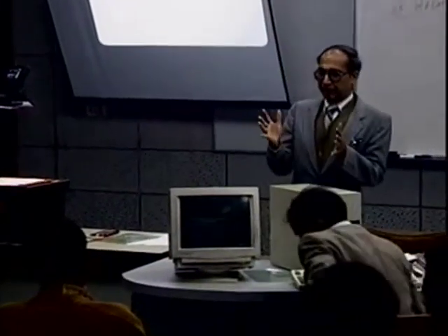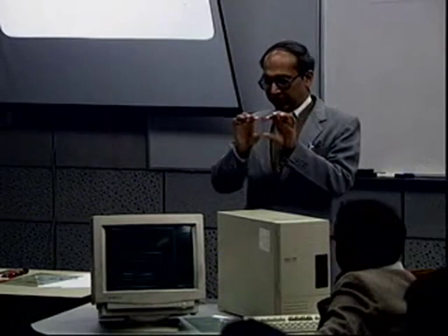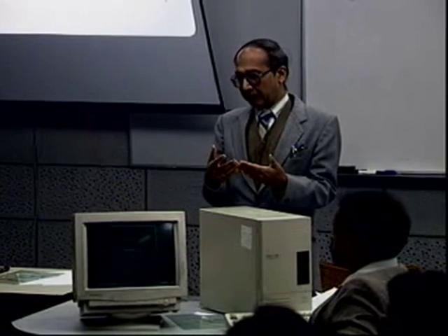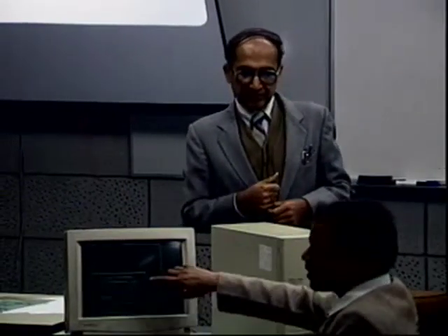Okay, so we have basically worked out that U-type electromagnet with mild steel bar and also with Alnico bar, and you will understand Alnico bar has different properties in the circuit because it is basically a hard magnetic material. By using those material properties in the computer program, we can get different types of flux pattern. We will see how you get those patterns. Okay. So this is the U electromagnet.